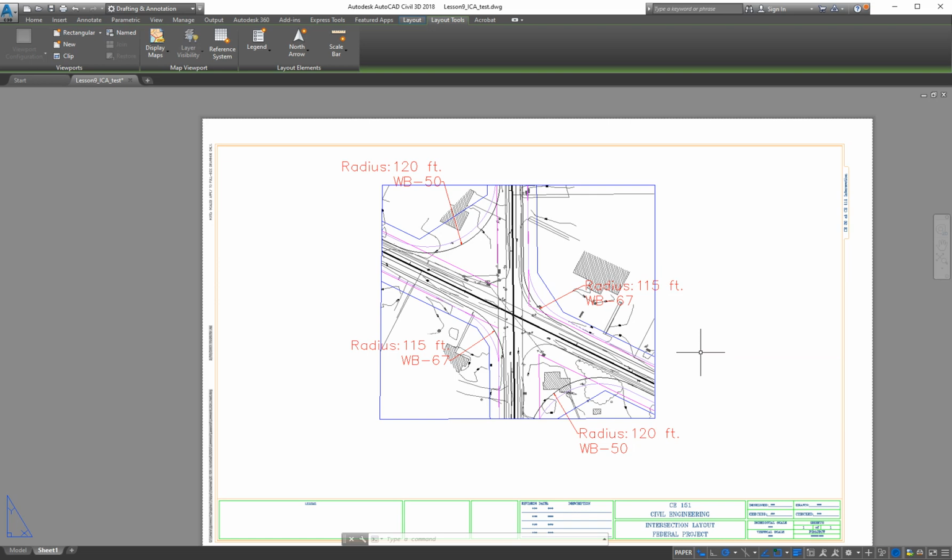So you may be able to see, if I wanted to do a detailed view of one piece of this drawing, I could blow it up at a higher scale and put it over here in its own little viewport. That's how we can use these multiple viewports on a single screen. And so that's the polygonal one. You can use other shapes, right? In fact, that's the next step. So that's 10 and 11 now.